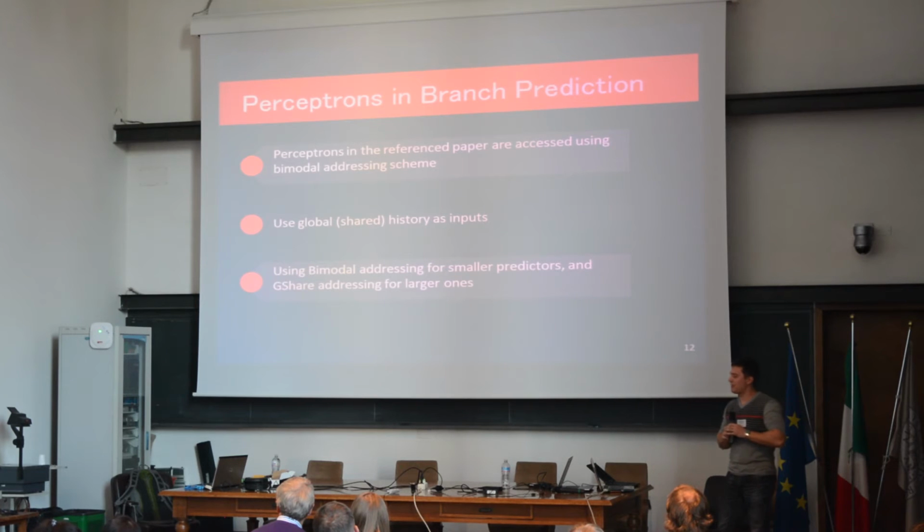And so there is a paper which already did this with perceptrons, and their approach was to use integer math because, well, basically there are only -1 and 1s in inputs and outputs. So in this case, the actual hardware implementation is quite simple because you only need to increment or decrement the weight, not use the product of inputs and outputs.